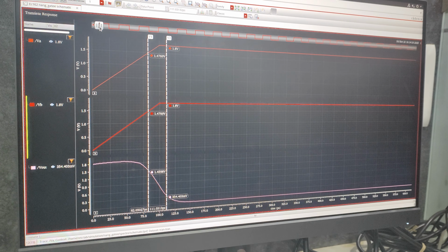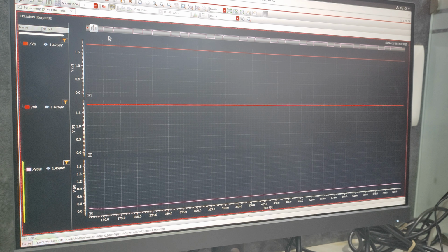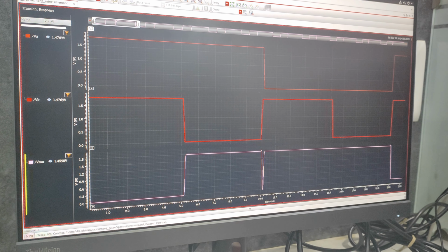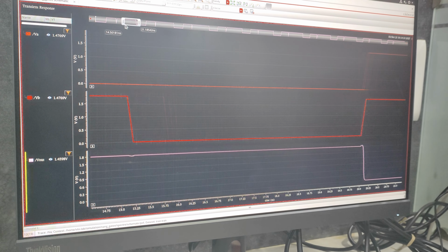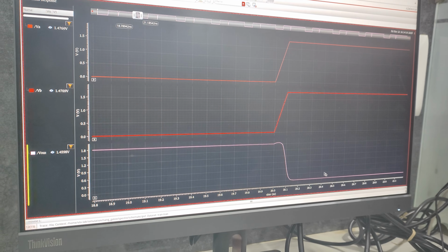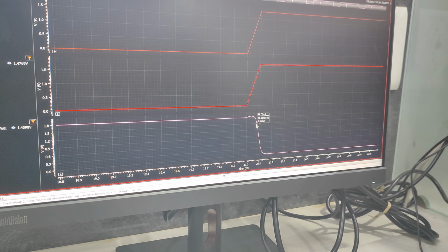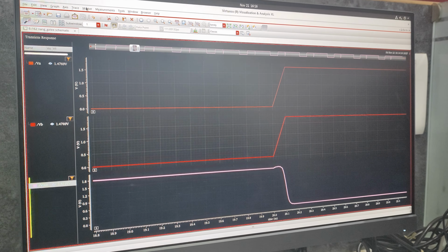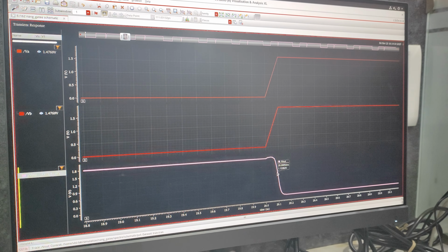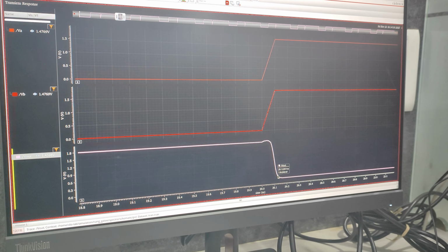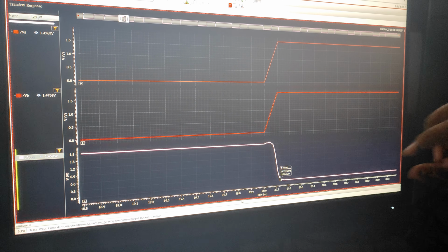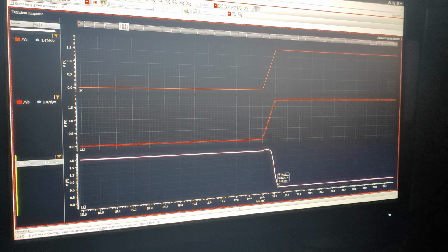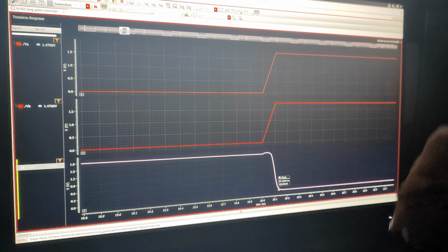Similarly, with the help of marker, click on this V out. You will know where the wave is falling. Let's say approximately over here, my wave is falling down. I'll zoom in to this particular point. See, here my wave is falling. Similarly, come to 1.44 with the help of a cursor or the marker, create marker, come here to 1.44. Similarly, 360 millivolt. Then with the help of those timing values, subtract the difference. So with these differences, you'll be getting the fall time.